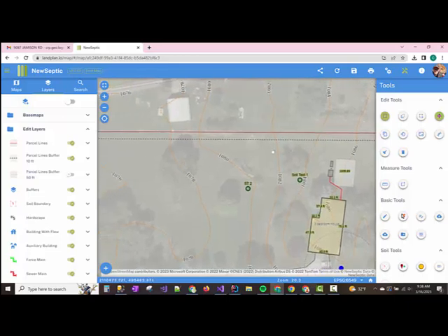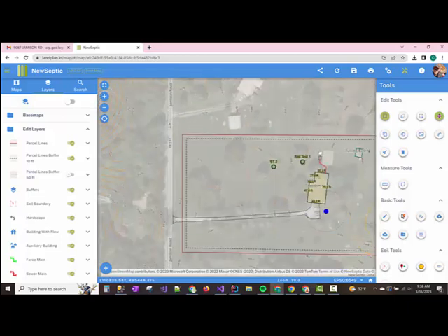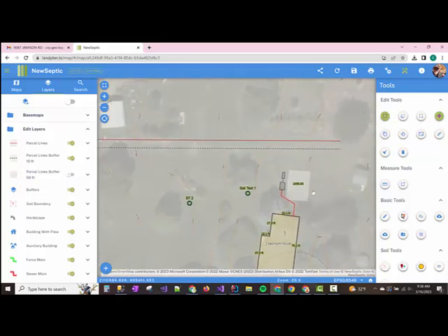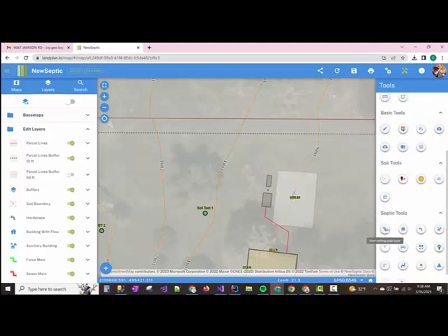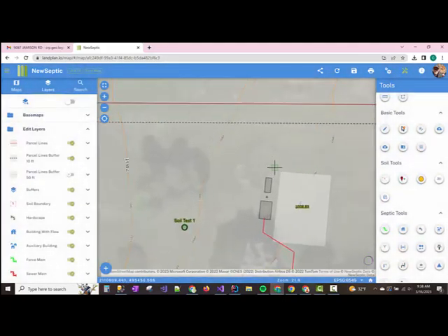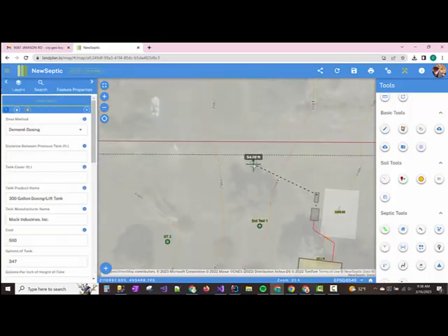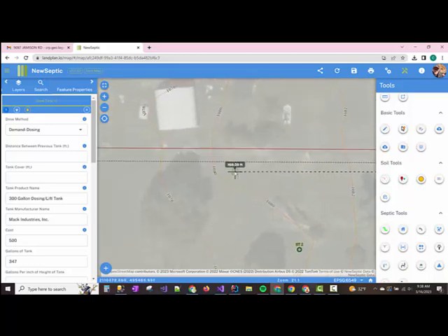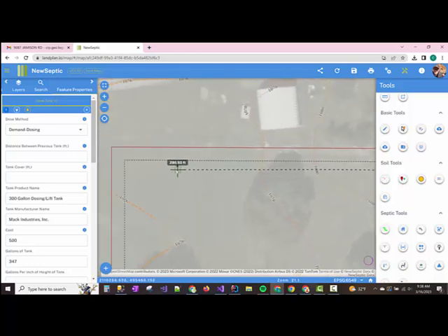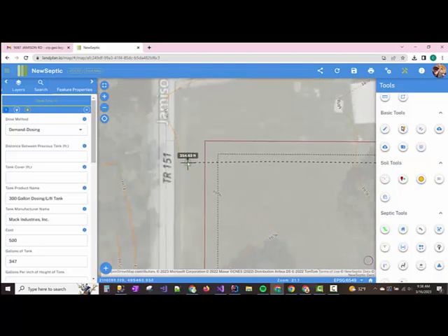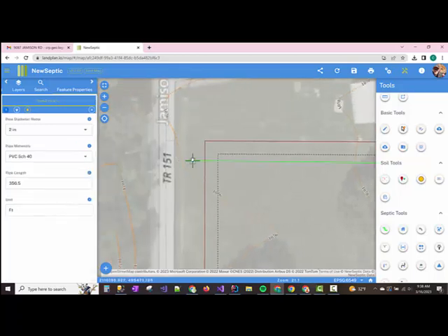So all right, I'm going to have to draw a force main that's going to discharge this water up to the road. So I'm going to go ahead and navigate to the pipe tools. I'm going to get the force main tool for the pump line. I'm going to click on the dose tank, zoom out a bit and just come and hug this property line up here. And then I'm going to double click at the road. And I'm going to set this to 1.5 inches, and then we'll just round that up to 357.